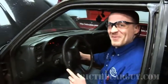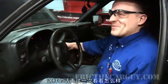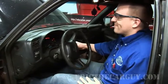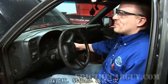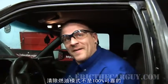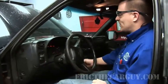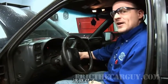All right, so sequence is important too. In this case, I'll just try it again. We'll see what happens. Pedal to the floor, turn the key on, try it again. You know, I just did this out in the parking lot. I really did. I promise. Go figure. Clear flood mode is not random. It is random, for sure. Let's try this again, one more time. There it is.